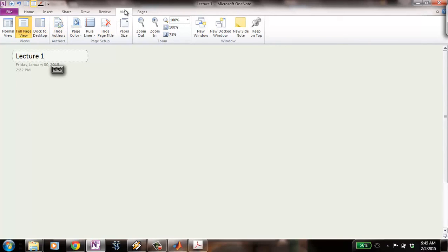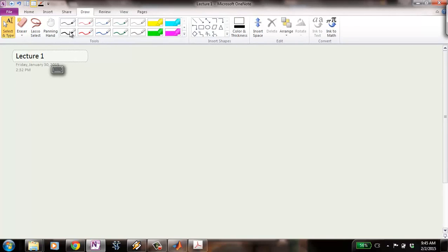Let's just, boy, what can I do in a few minutes here? Well, so in general, we're not going to restrict signal values to be real value. They can be complex value. And there's a very important reason why we're doing that. Okay, you might say, well, real world signals are real numbers. Yeah, you don't have a sensor that gives you a complex voltage. It's got a real number voltage, right? But if you extend things out to complex numbers, the math is a lot simpler when you're doing things like Fourier transform. The Fourier transform is going to explicitly use complex numbers everywhere.